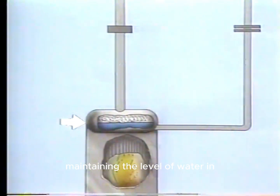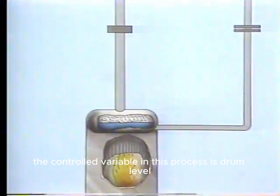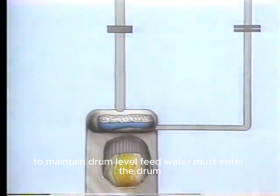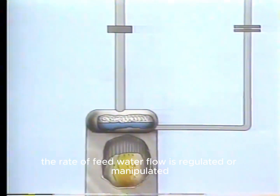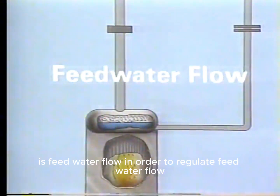Maintaining the level of water in the drum is essential to the proper operation of the boiler and also to boiler safety. So the controlled variable in this process is drum level. To maintain drum level, feed water must enter the drum at the same rate that water leaves the drum as steam. To do this, the rate of feed water flow is regulated or manipulated. So the manipulated variable in this process is feed water flow.